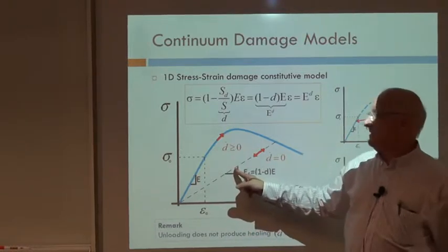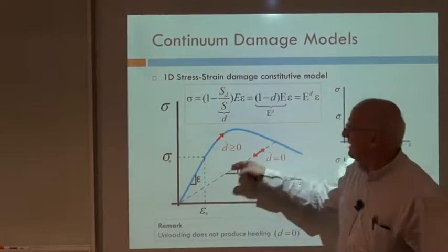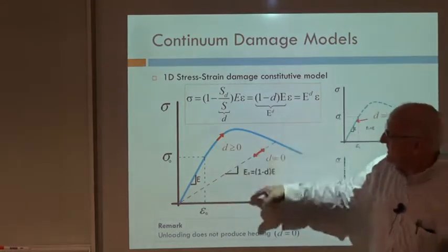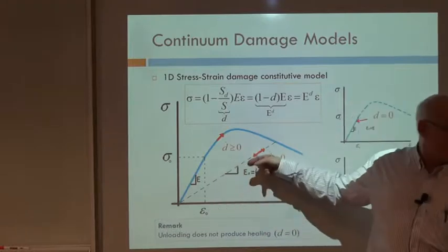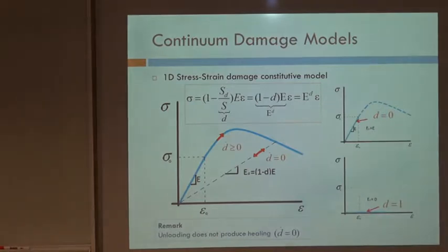Why elastic? Because we'll prove that here there is no dissipation. And while I'm keeping the stress state, strain state in this branch, it behaves like an elastic, incrementally proportional. But this is not the elastic range. Why do we call it elastic loading?